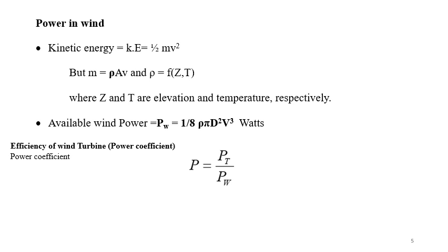Okay, so power coefficient is defined as the ratio of power of the wind rotor to the power available in the wind, that is Pt, the power of the wind rotor at the turbine, divided by the power available in the wind. So where power available is calculated from the air density, rotor diameter and free wind speed as shown above.